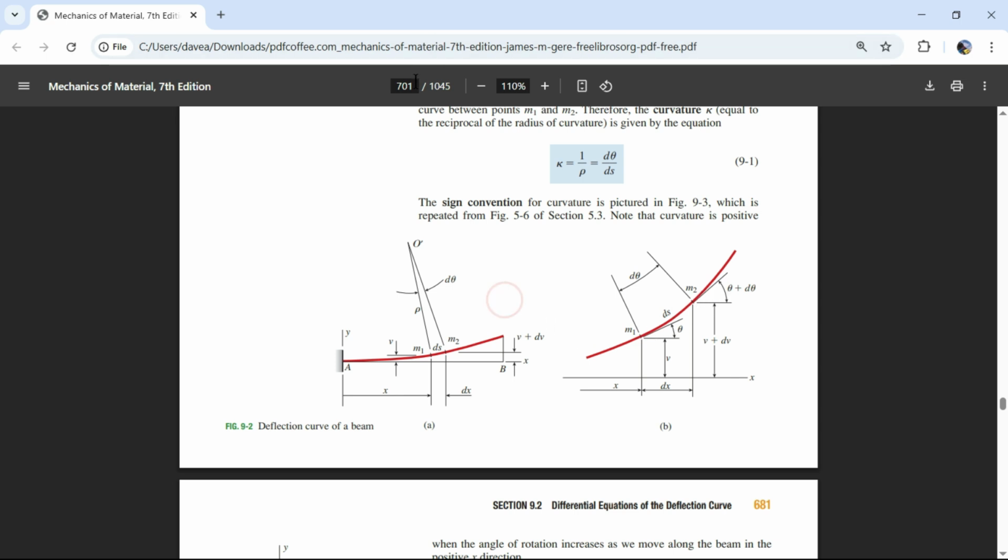Okay, so let's go back, because this is not pure. You can have a cantilever generating a pure moment at the end. So, if there's no loads on here, sure, you can just apply a moment on this end, and that moment's going to be the same throughout. And if you have a constant moment, this whole shape will be an arc of a circle.